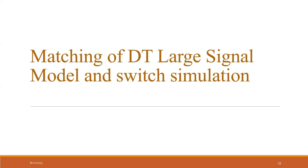Then we superimpose it and show that they match. That means the discrete time large signal model which I have derived, after checking each mode of operation from one state vector to the next, is valid and is matching with the actual simulation which I'm doing in Simulink.